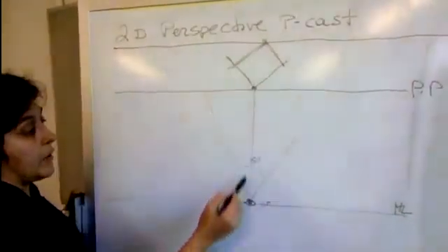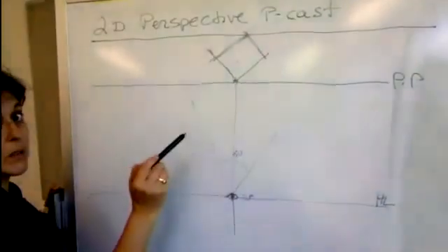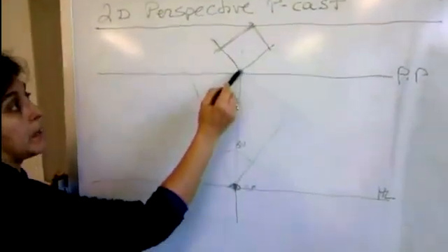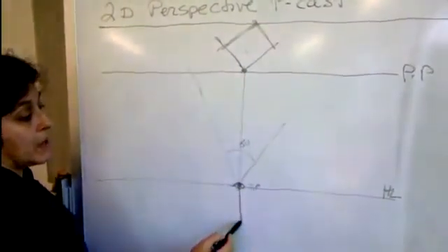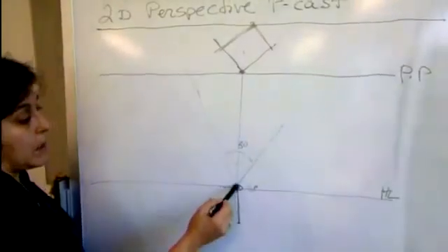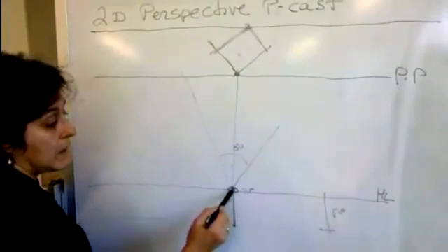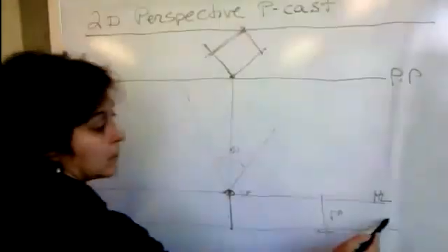Anything on this line now is to scale at the same scale as the drawing. So the height of the building at that corner can be scaled now along this line. I measure 5 feet down from this line to find the ground plane.